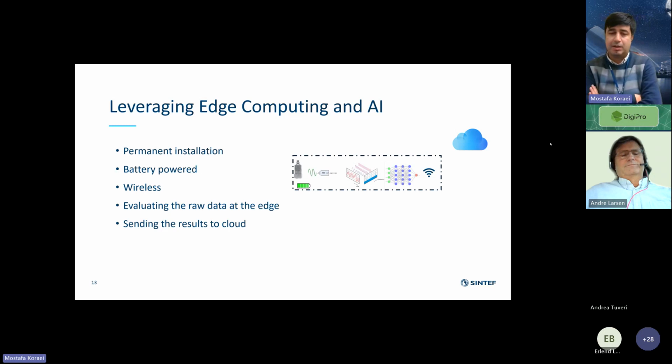We can, yeah. This system is quite sensitive. The sensitivity is in the range of minus 130 dB, so you definitely detect the trucks or transformer or any kind of vibration in that area. But what we do is use our signal processing to isolate that vibration from the vibration that we want to detect from the target equipment that we attach the system to.